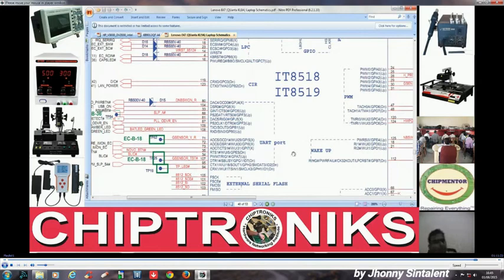There are two fixed specific ports. One is 60H, another is 64H, right? 60H and 64H. That is, our CPU can communicate with the keyboard controller present inside a desktop keyboard.